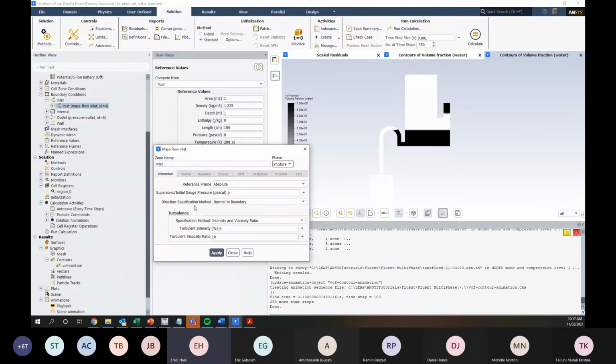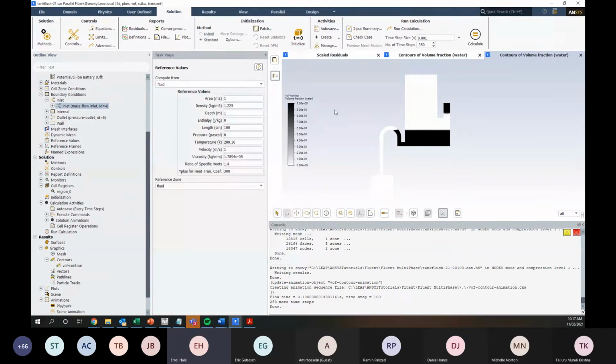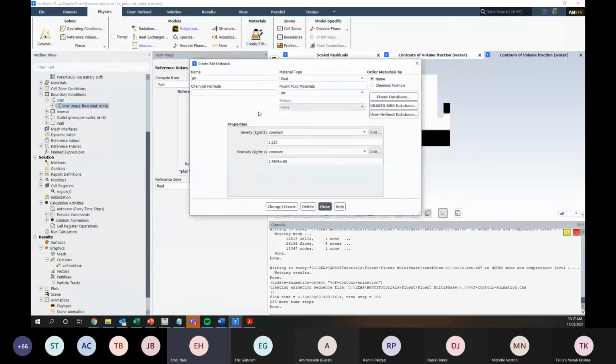How is the viscosity different between the two phases modeled in Fluent? Well, the viscosity is specified in here. So the viscosity of air, it's obviously going to be a lot lower than the viscosity of water, but each of those fluids has its own viscosity. So that'll be factored into your Reynolds average Navier-Stokes equations in your mass continuity, I believe, in your pressure continuity Reynolds average Navier-Stokes equation.